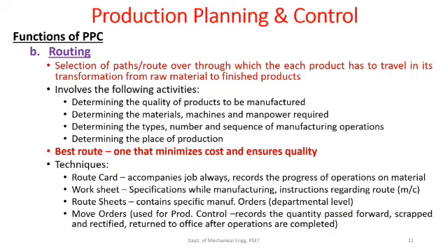There's a particular order in which they have to be carried out, and sometimes in a threading operation you might have to make multiple passes. So the number of times a particular manufacturing operation is repeated is also of significance, and that is determined by the quality of your product. For example, if you are using a finishing operation, say grinding, to finish your product at the very end, sometimes you might have to use multiple passes of grinding to get the required finish.